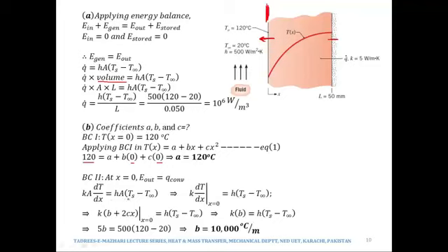The same energy will be further transferred via convection, and this will be true because the energy conducted from one point to the other is the same as the energy conducted from the second point to the third point. This equality will hold true as long as the system is under steady state conditions. Otherwise this equality will not be true. So the areas will get cancelled out, because it is the same area through which conduction is taking place and through which convection is taking place. And we will have k dT by dx at x equal to 0 as h times delta T.